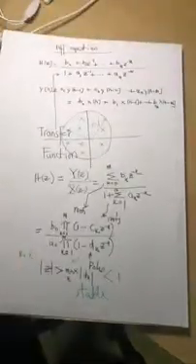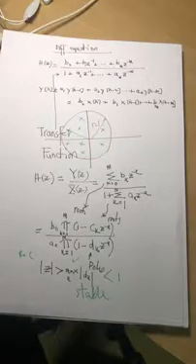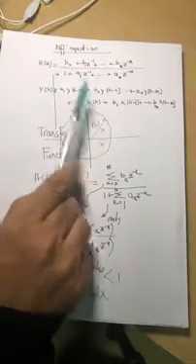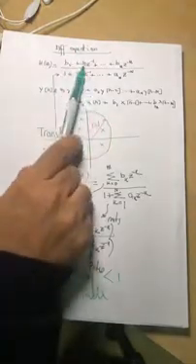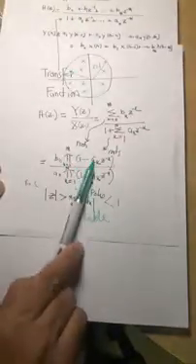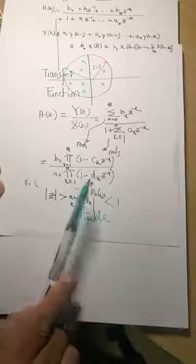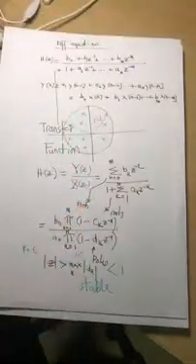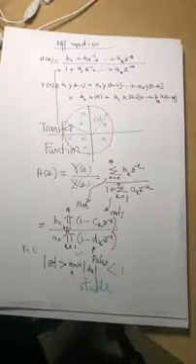So going from the difference equation, constituting a transfer function, converting the transfer function into poles and zeros, and finding the pole with maximum magnitude will answer the most important question while dealing with IIR systems, whether your system is stable or not.